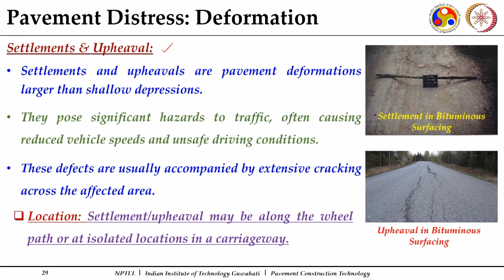Settlements and upheavals are there. At certain locations you will see some settlement and some upheaval of the pavement layers, the bituminous layers. That is another kind of distress which will come under the category of deformation. These are permanent deformations larger than shallow depressions. For shallow depressions we consider a depth of around 25 mm. If it is more than that, we will call it a settlement.